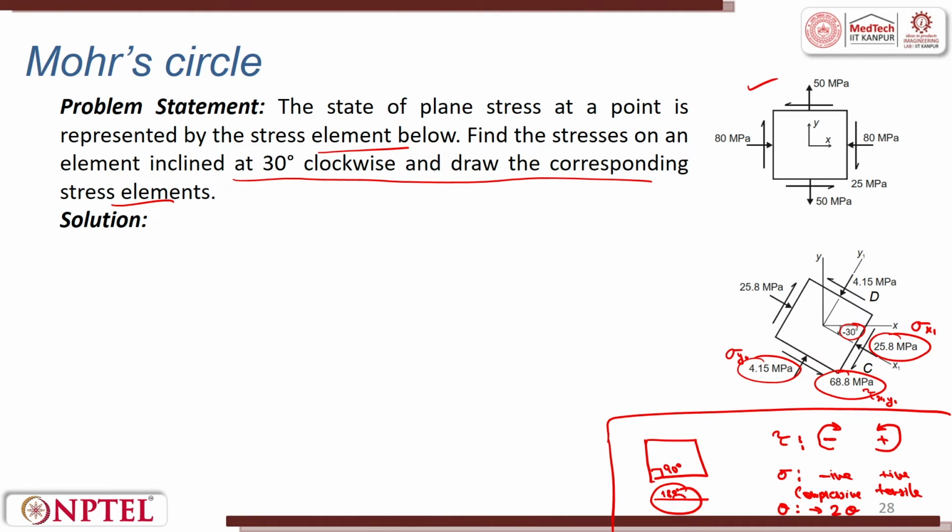Talking about the Mohr circle here, we know we have the normal stress in this direction and the shear stress in the y direction, it is tau. Let me first try to plot the points A and B here. A is sigma x, tau xy.